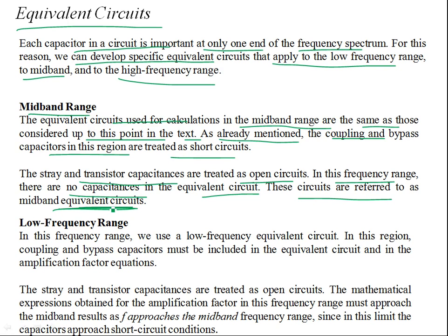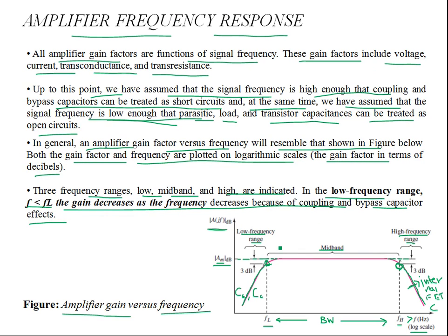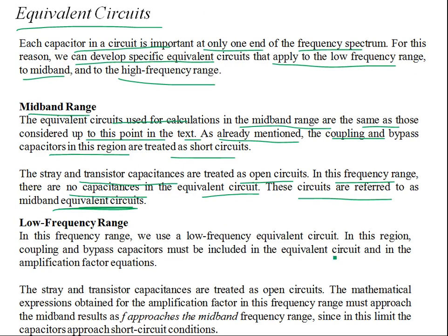those are circuits that don't include the effect of such capacitances, because the frequency response happens to be independent of such capacitive effects, and it's independent of the frequency. Okay, the gain stays constant. So we are not going to include any effect of capacitance in the mid-band range. All right. So for the low frequency range,